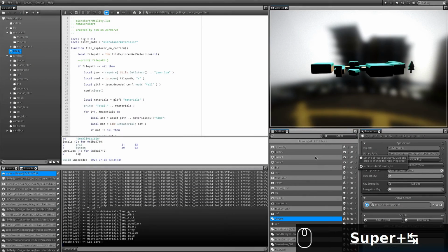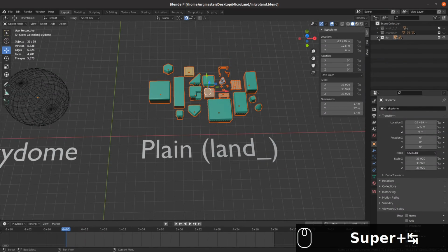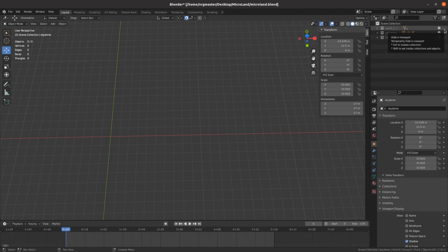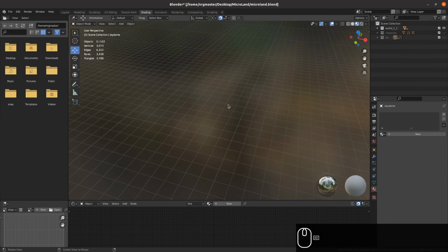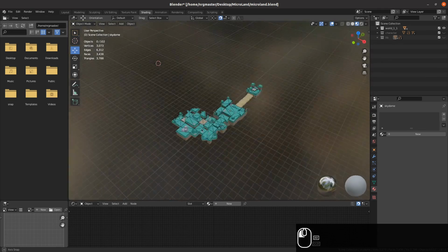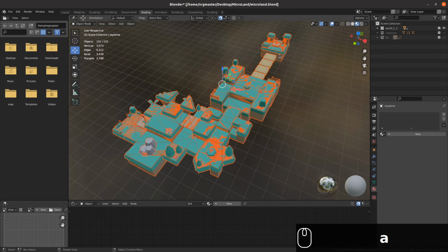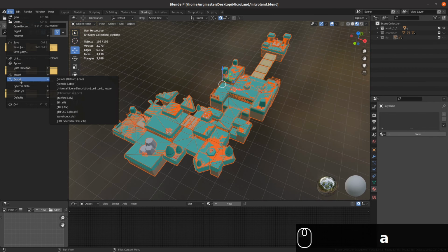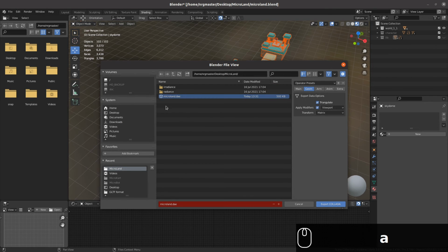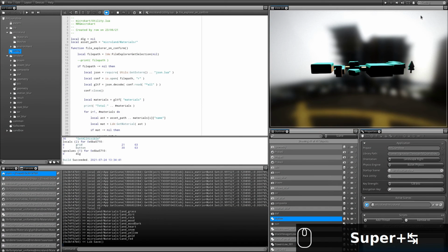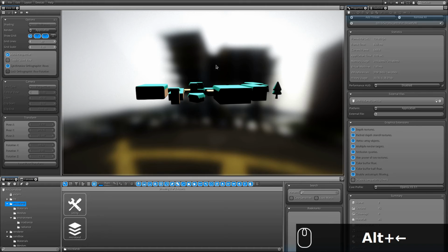To import our level, we're going to go back to Blender, and this time I'm going to turn off the visibility of lib, and I'm going to turn on the visibility of world 1. If I go under shading here to have a better look at how it's going to look, this is our first level. So what we're going to do, we're going to push A to select everything, and we're going to go under File, Export, Collada, and select our microland.dae. We're going to override it. Ensure that in the main selection only, geometry triangulate and apply viewport modifier are on. Export that. Done.